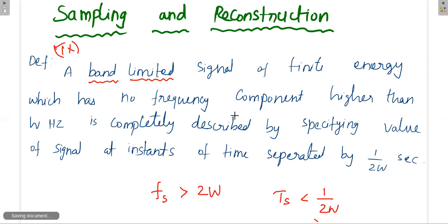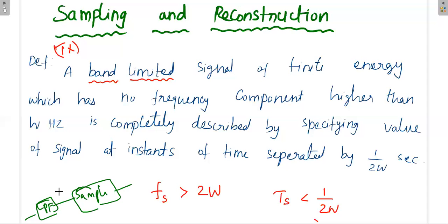In future, to get the band limited signal, we know that before sampling we always use a low pass filter. It is mainly to band limit the signal, because we should know the maximum frequency in the signal, and then only can we apply the sampling theorem. Again, we may think that the original signal passed through a low pass filter may lose some information.